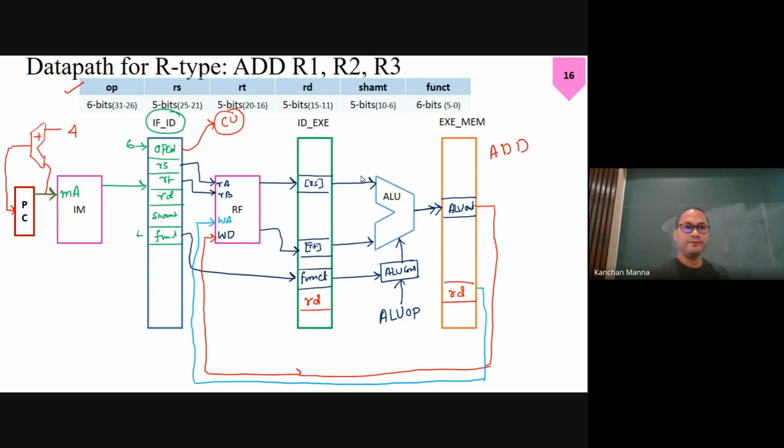Now, did you understand his question? He's saying that in the multi-cycle approach, we did this PC plus 4 using the ALU, right? Now, if we perform that PC plus 4 through the ALU, what will happen? We cannot fetch the next instruction, because at least it should wait. Got it? So we want to fetch the next instruction after that clock cycle, right?